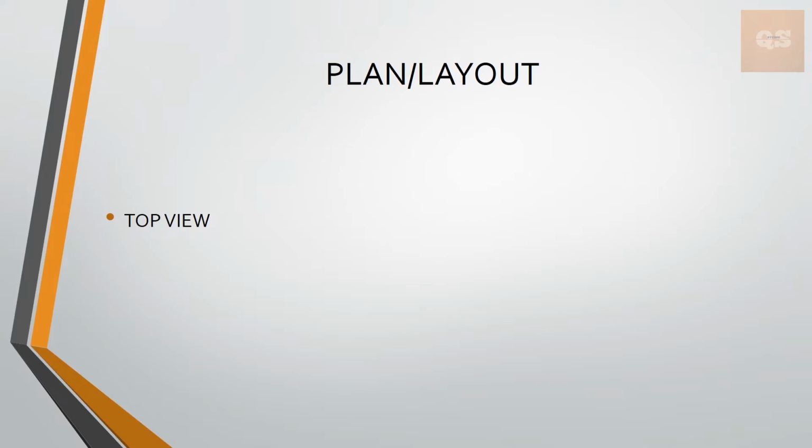So what is plan or layout? Basically this is a top view of what you are seeing. It can be a layout of a floor. It can be a layout of an external area. So when you see this part from a top view, that is what you get to find in a plan or layout. Mostly for a quantity surveyor, 70% of your quantity takeoffs can be done using a plan or layout, and the remaining 30% lies on the other drawings. So this is a very critical type of drawing that is involved in a construction project.